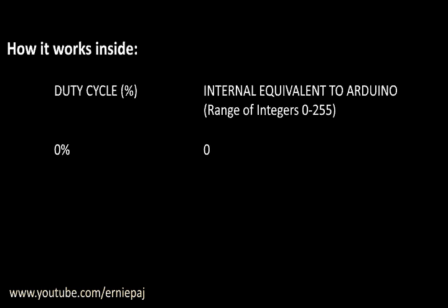Within the Arduino clone, the duty cycle or percentage of time the signals or pulses are in a high state can be represented by a variable declared using the analogWrite method within the Arduino IDE. As you change that variable within a range of integers 0 to 255, you will be able to control the available effective percentage of power sent via pin number 9, which is 5-volt DC.